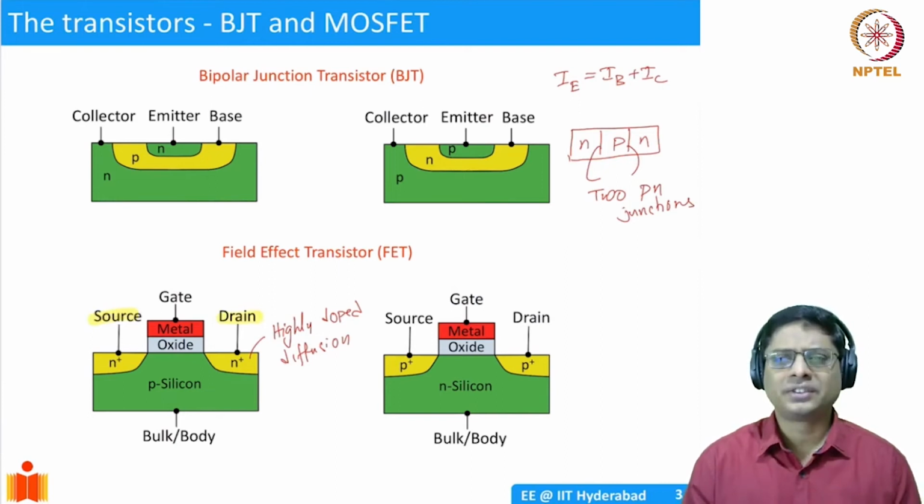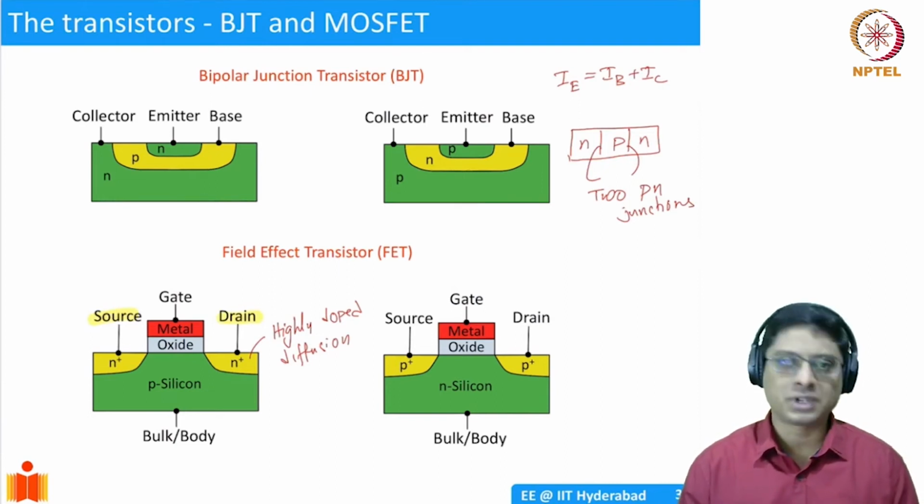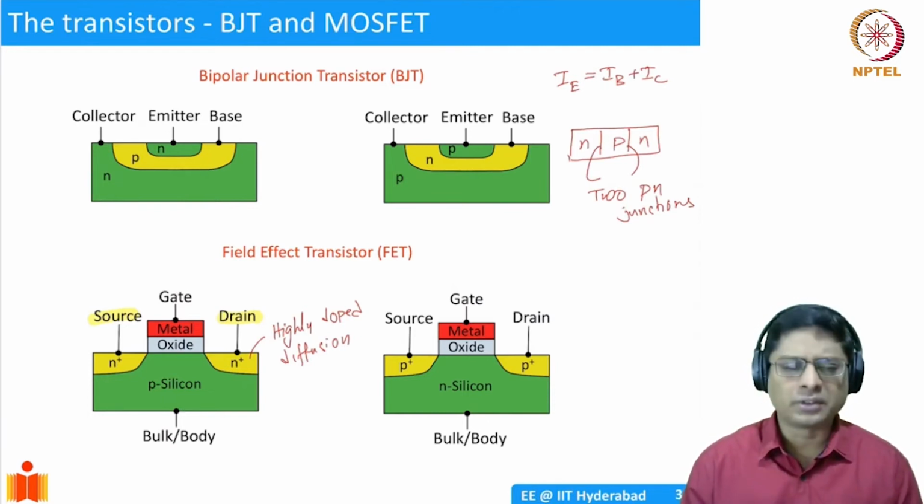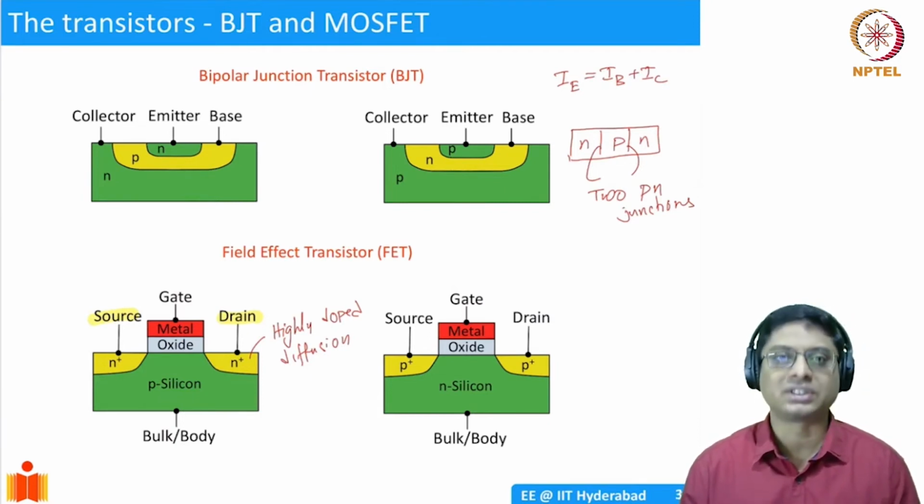Physically there is no real difference between a source and the drain. It's just a matter of what voltage we are applying to it. That's why the convention comes about. But in terms of doping, typically they are symmetric. You can interchange the drain and the source and nothing much happens. The transistor would still work.